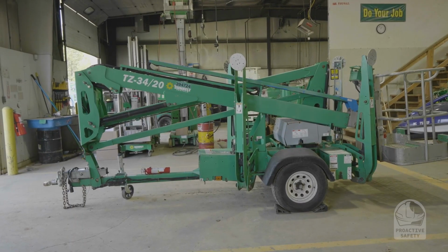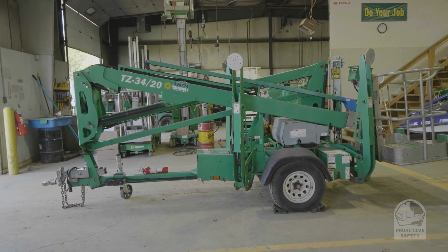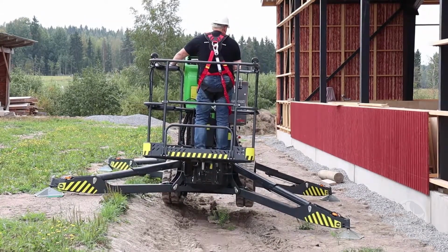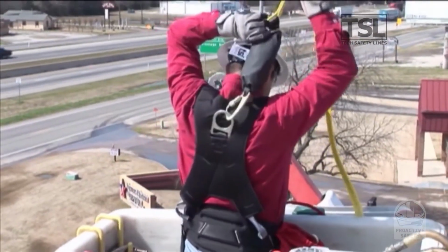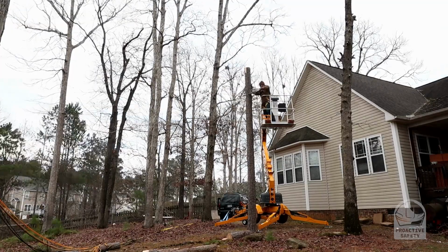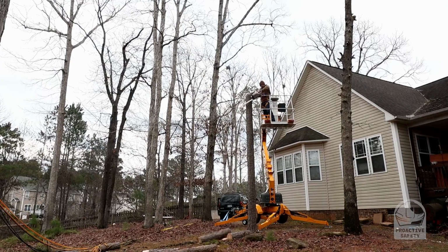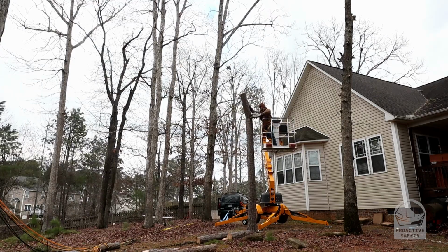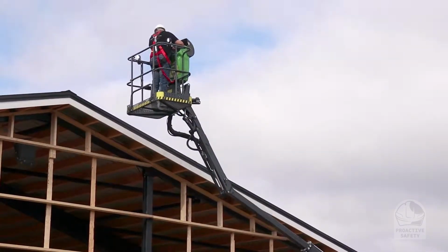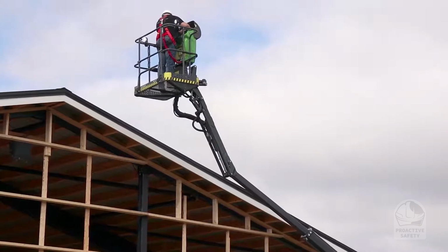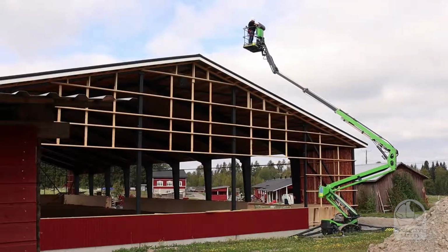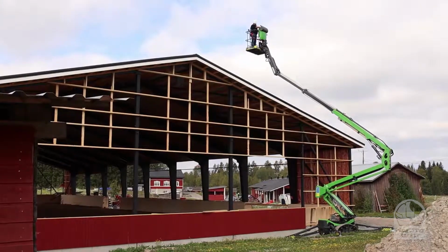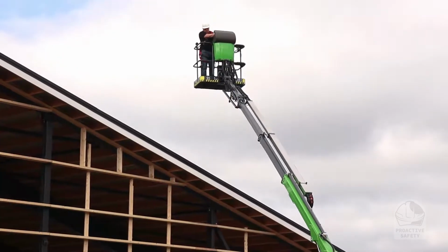Leveling the equipment before lifting it is very important. And make sure to use your seat belt. Maintain the raised railings. Control of speed and orientation of the equipment must be regulated at all times. It is important to maintain constant communication with all surrounding workers or pedestrians. Remember to respect the slope limits and load capacities of your machine.